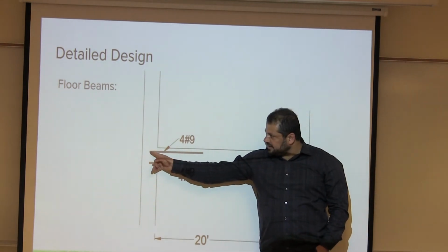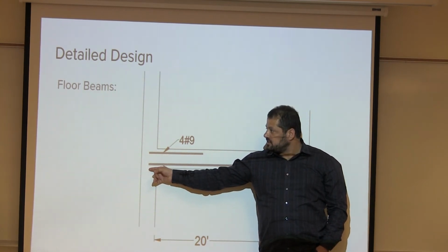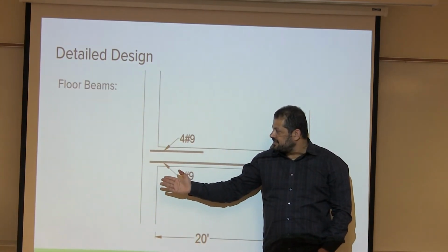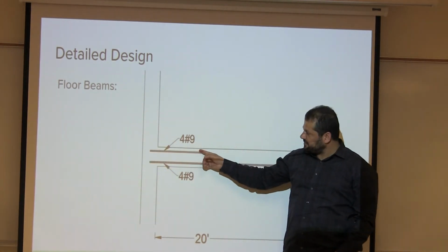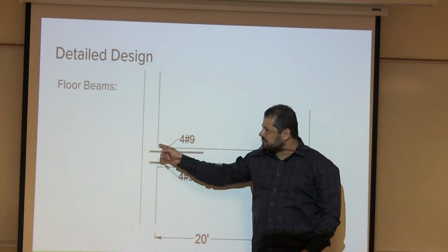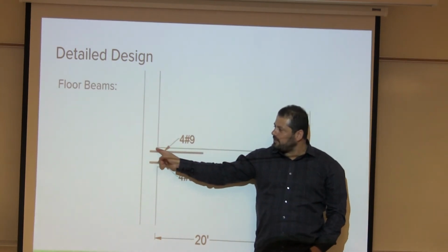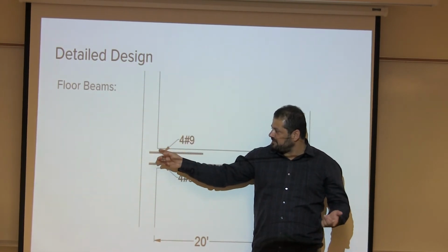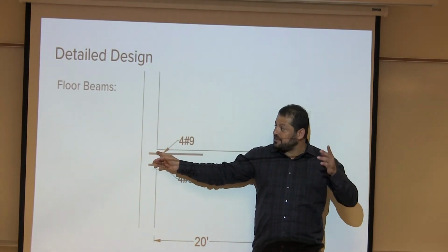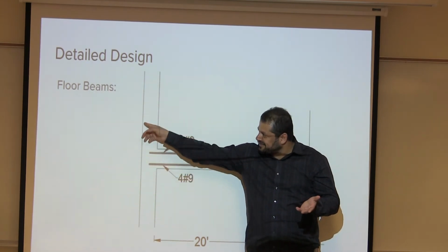But when you have something like that, the recommendation is to go 6 inches, right? That's why you just want to show that it goes 6 inches. But this will not give you any accurate fixation. If you want to create some kind of fixation, this reinforcement must be anchored so that it gives you a Fy in here. If you want to have a negative moment in here, your reinforcement must give you a Fy, so this must be greater than the development length.